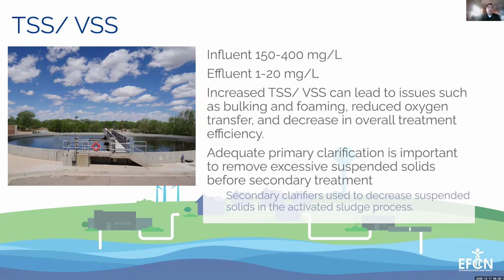A couple things I like to point out about the TSS and VSS is that increased TSS and VSS can lead to issues such as bulking and foaming, reduced oxygen transfer, and decrease in overall treatment efficiency. So we'll make sure that we're not exceeding those limits, or our bacteria will grow out of hand and exceed what we needed for treatment.